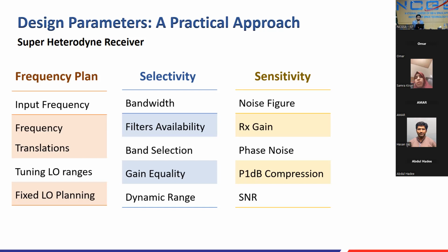Then there's another aspect, the most famous. We have already covered the SNR and the minimum detectable signal. SNR usually is a user-defined requirement. So the user will also tell you he wants to sample the signal at 3 dB SNR, 10 dB SNR, 20 dB SNR, based on which application the system is being implemented, or what the particular purpose of your hardware is that they are fetching from you.